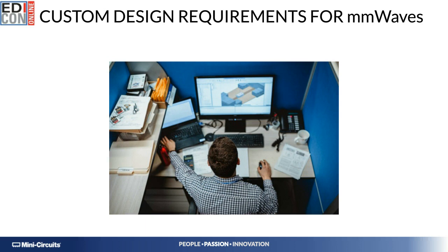Designs such as bandpass filters are varied from application to application on center, cutoff, and stop and rejection frequencies, as well as levels of insertion loss, return loss, and so on. When you cater to more than 20,000 customers, as we do here at Mini-Circuits, believe me, there are many flavors to a bandpass filter request centered at the same frequency.